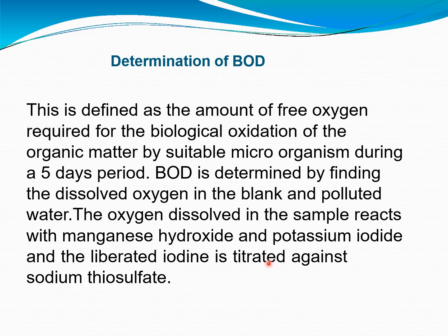The next one, two important determinations are there. One is BOD determination, the other one is COD determination. Let us see how to determine the biological oxygen demand value for the given sample. What is BOD? It is defined as the amount of free oxygen required for the biological oxidation of organic matter by suitable microorganisms for 5 days. BOD is determined by finding the dissolved oxygen in the blank and polluted water.